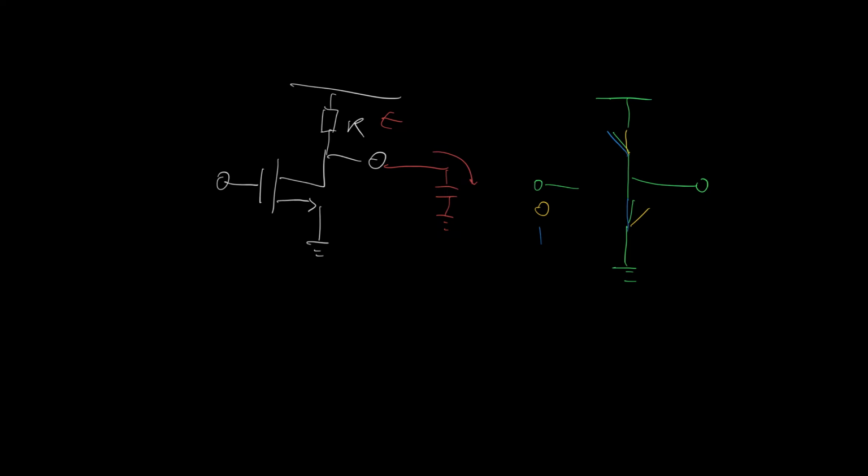So what we require is two switches that function dual to each other. When one's shut, the other's open. We can achieve this quite easily by using an N-channel FET at the bottom and a P-channel FET up on top here.